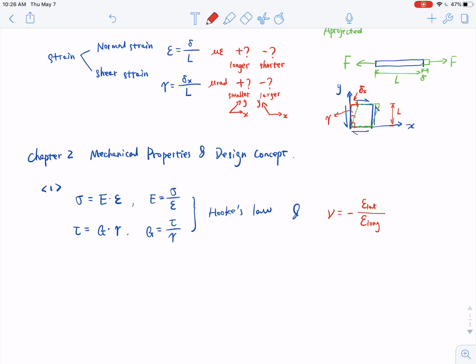In the slides, you saw that our Poisson ratio is normally 0 to 0.5 for normal engineering materials, right? So the upper limit 0.499 is for rubber. Other normal engineering materials like steel, concrete, their Poisson ratios are just between 0 and 0.5. For concrete, it's normally 0.2 to 0.3, or 0.33. That is a normal range of a hard engineering material. But it's a positive number, right?